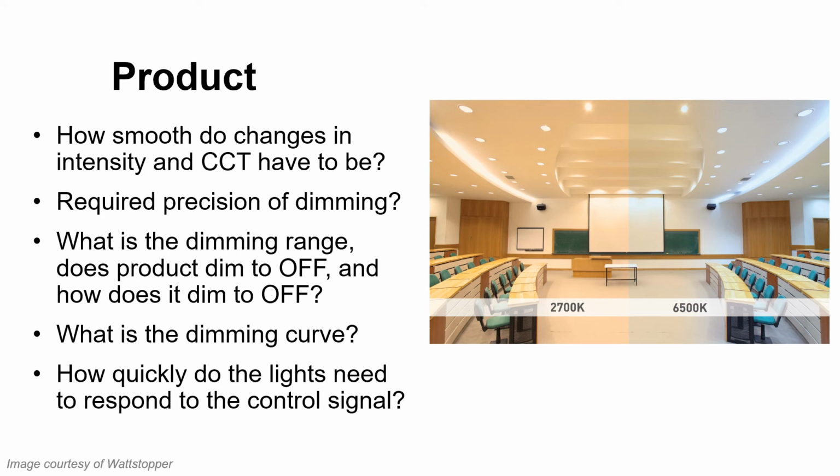How quickly do the lights need to respond to the control? A DALI-based system may take 2 seconds to respond, which may be fine for many commercial applications, while with DMX, system response is nearly instant.